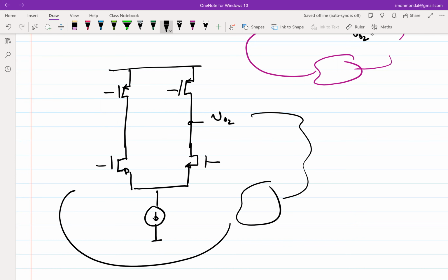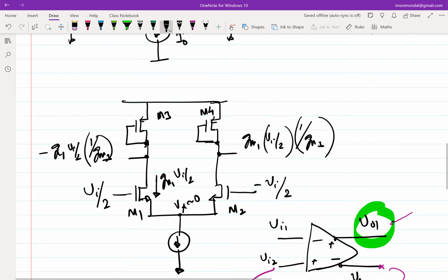But what is happening to V01? V01 is not in feedback. But since we are not particularly interested in taking output from V01, we can still localize its voltage through negative feedback, right? So there is nothing stopping us from doing this from V01. Do you agree? Okay.